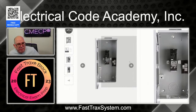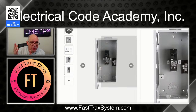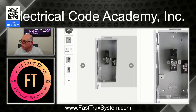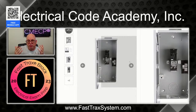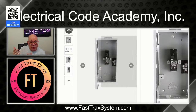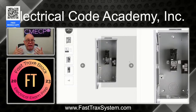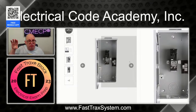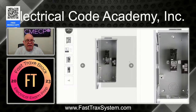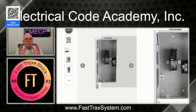And that's going to feed my panel somewhere else, which could be main lug only if I want, because I've got the protection upstream. And of course that might save you cost-wise because you don't need another main breaker. Now, if you want to get a panel with the main breaker because of cost and supply, that's okay too. You can have two. That one's just going to be basically a switch, even though it's probably still going to have an overcurrent rating on it, but you get my point.